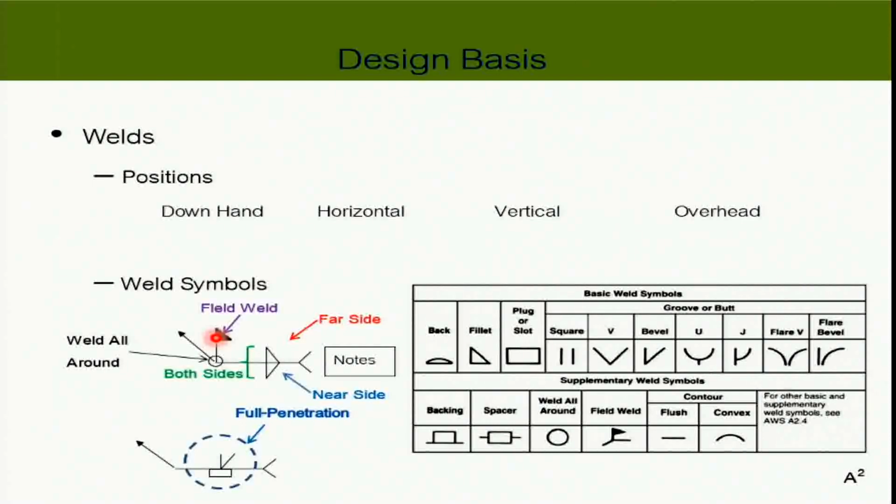And you can always include extra notes to make sure that the welders understand you by giving the size of the weld, the length of the weld, and the strength, and so on and so forth, okay? It's not a time to say, I'm just going to keep the information to myself because I don't want you to know it. If he doesn't know it, how can he weld correctly, right? So you need to give as much information as possible.